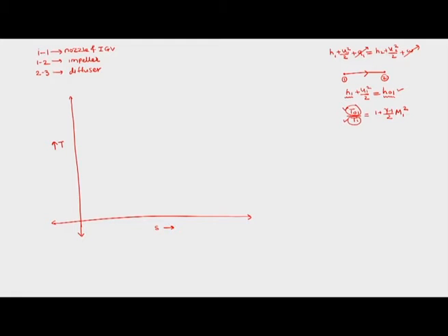Whenever we were dealing with the Brayton cycle in earlier chapters, we were considering the TS diagram, and for the TS diagram we were considering only static temperature. So for us compressor work was Cp into T2 minus T1, our turbine work was Cp into T3 minus T4. This was a simplified analysis where we had also stated at that time that in both the cases we are considering gas to be calorically perfect, plus we are considering flow to be adiabatic, plus we are considering that the kinetic energy is negligible in terms of the enthalpy.